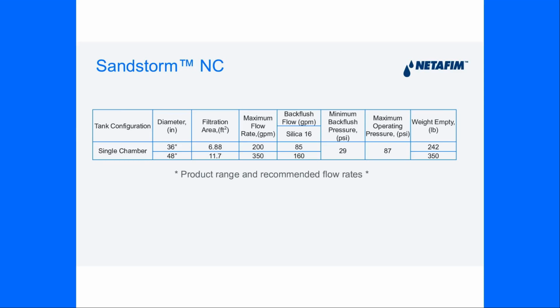If you had perfectly clean water, from a municipality, for example, what we're telling you is, if that was the scenario, you could run these maximum flow rates through it. But generally, as a friend of mine would tell me, if we have super clean water, do you really need a filter, right? So we really focus on what's the application, what's the water quality, and then in our technical guides, we do have some recommendations on maximum flow rates for average water, poor water, very poor water, etc.